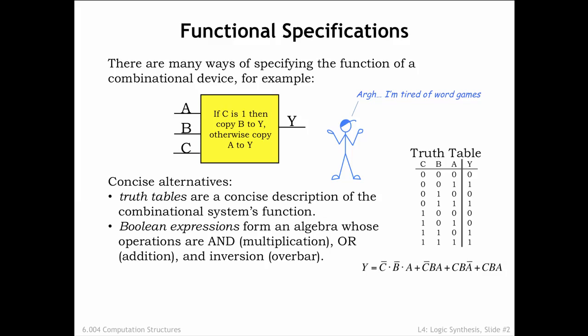The operations we use are the logical operations AND, OR, and XOR, each of which takes 2 Boolean operands, and NOT, which takes a single Boolean operand. Using the truth tables that describe these logical operations, it's straightforward to compute an output value from a particular combination of input values using the sequence of operations laid out in the equation. Let me say a quick word about the notation used for Boolean equations.